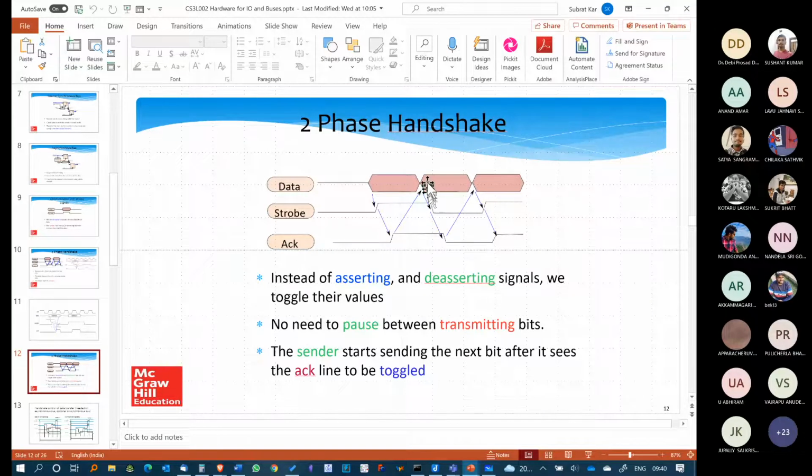So if you send this data and you don't send the strobe, then I'm not going to sample this. You can do whatever you like, but until you send the strobe, which is here, I'm not going to do anything with the data. So I will actually, in this, miss this data because you are not sending any strobe with it. That's up to you. So the two-phase handshake will suffer from this: this particular middle data set will not be sampled.